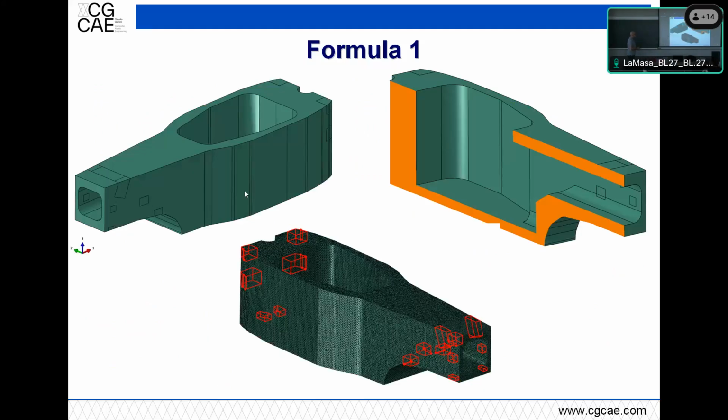The other thing that might be asked of a stress engineer in motorsport is optimization. I don't know if you know Altair OptiStruct, which was coming out in exactly those years, 2001, 2002, for topological optimization. So you get a design space, so where your structure can be. You have your boundary conditions, you have your load conditions, and you let the software run and say where it needs to put material to minimize the overall strain energy.